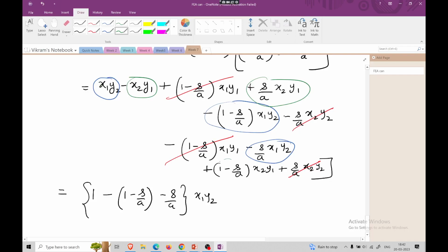So this is a long question. So what we intended was we have to calculate the psi I. Psi I we have calculated in the S and T coordinate system. So now we can develop the QI, right? So what is Q1 for this element? It will be integral over the boundary of the element Qn into psi 1 into ds. Okay. So in this case my Qn is nothing but it is given to be Q0, correct?